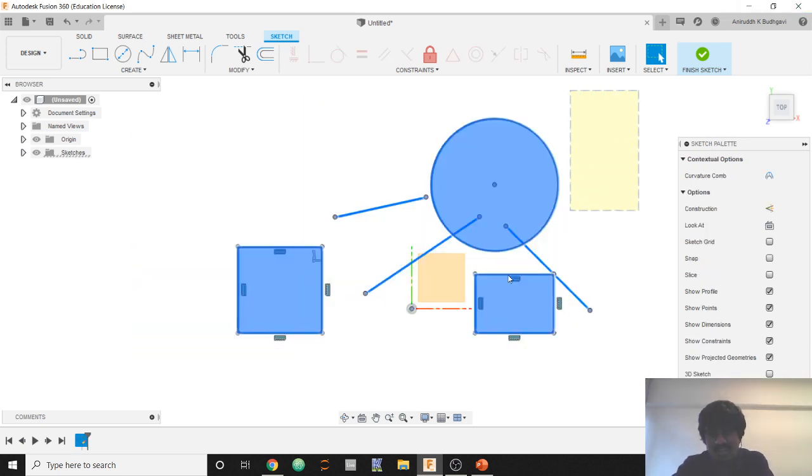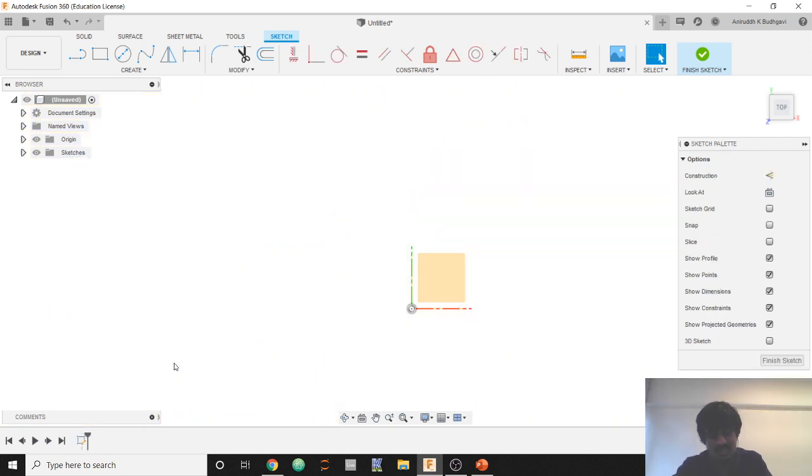So I just click drag and press the delete key to get rid of all the features. Keep in mind that deleting things is actually a bit dangerous sometimes, because the way Fusion works is it doesn't just maintain the current state of your model. It starts off by maintaining the entire history of the model. Everything is maintained in a timeline, and if you mess with that timeline, things can get a little weird.